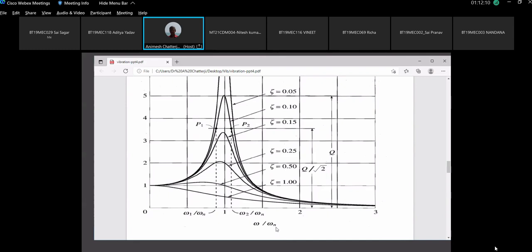Can I change omega n? Yes, sir, by changing the isolator stiffness. The mass of the machine I cannot change. Omega n is square root of k by m. The mass of the machine I cannot change; we cannot cut the machine in half. But for the isolator, I can now go for another isolator. So I can change K. So omega n I can change.